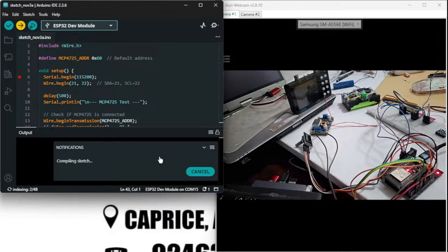So this is the multimeter that I use. It can also generate a signal waveform. So I've placed it on the signal waveform so that I'll be able to do my calibration successfully. Let me connect ground to ground. Then let me connect this to, yeah. Instead of doing auto on the waveform, let me do my own settings.